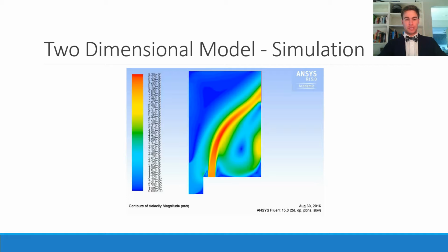Additionally, a swirl entrainment from the A-recycle pump propagates for the duration it takes for full flow to be achieved, which is approximately 3,000 iterations at steady and SIMPLE. The swirl entrainment that propagates from the A-recycle pump to the outlet results in the region experiencing a velocity around 0.3 meters per second. The region in the top left-hand corner, where the submersible mixer is located, is subject to velocities below 0.3 meters per second, and therefore settlement of microorganisms may occur in the region, which may result in undesirable biological conditions.